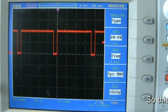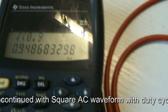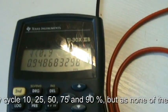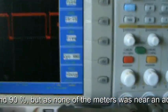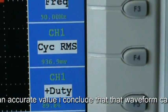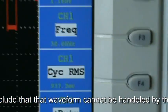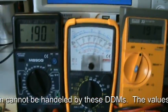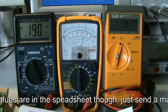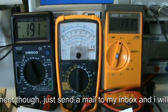So when I calculate via this formula the RMS, it should be 0.94 volts, and this is close to what the scope is showing, but all the multimeters are way off, and that's for the whole range already with this low 50 Hertz frequency.